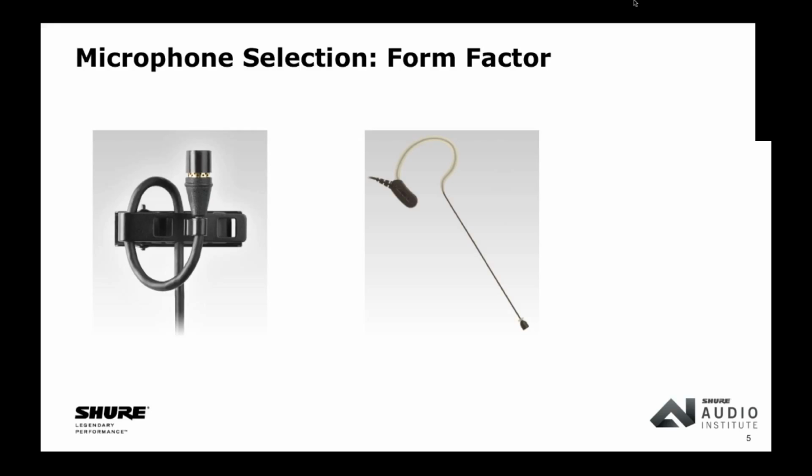An example of a show that we do at Shakespeare is the Q Brothers shows that are rap-oriented shows. And those shows, the show is very, very loud. And if they don't get vocal back on stage, they can't hear each other to be able to actually perform the show. Okay. So in those sorts of situations, we use a directional microphone. We actually put cardioid booms on them in order to get a bit more gain out of the microphone to help combat the loud monitors.